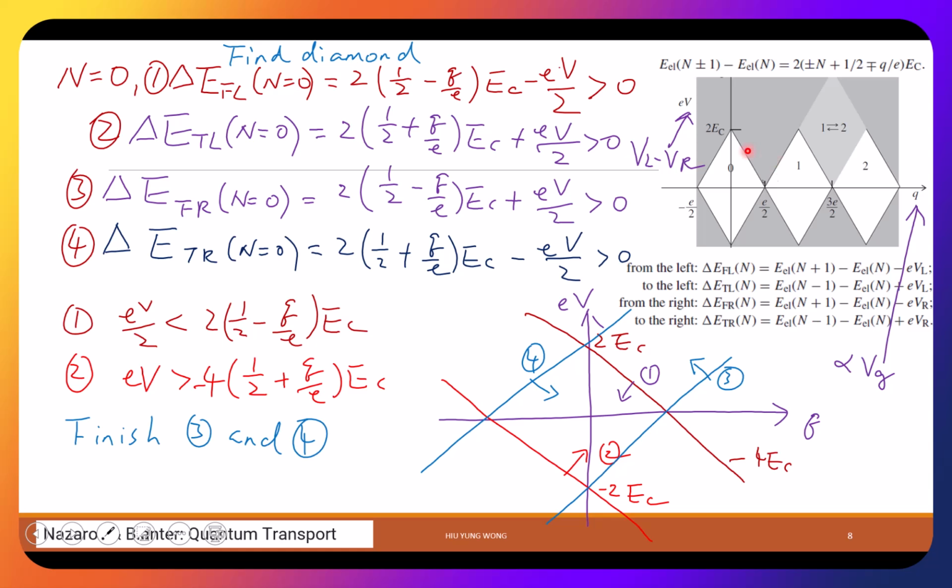For example, maybe you can bias it here. When there's no charge, then no current in the single electron transistor. When there's a charge, I'm talking about a charge outside of the single electron transistor, then you have current. As a result, you will feel the current, and then you know whether there's a charge or not. And there's something called spin to charge conversion that converts the spin information into charge so that you know whether your qubit is spin up or spin down.